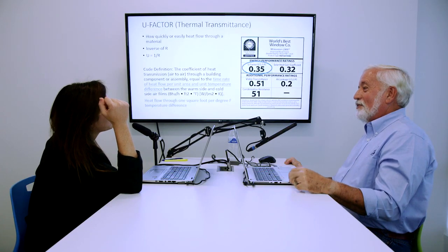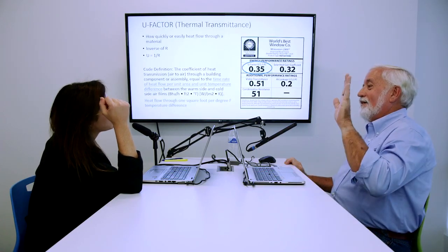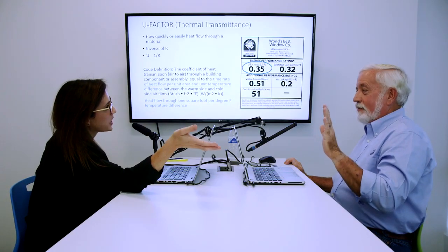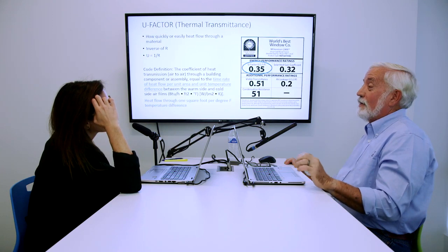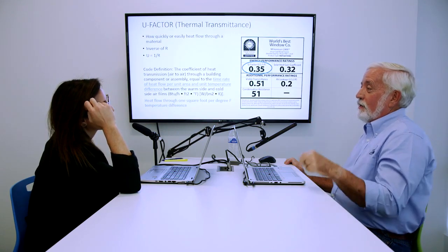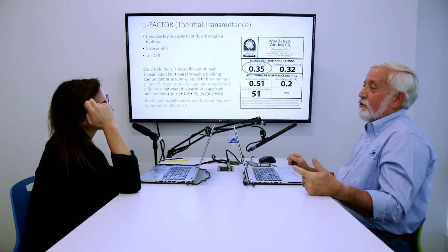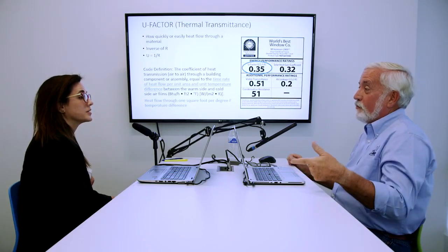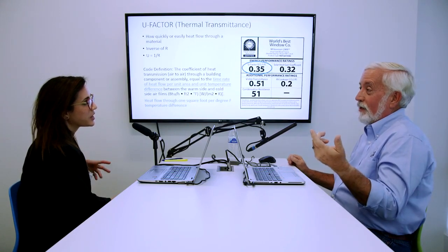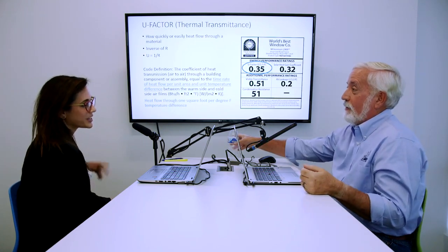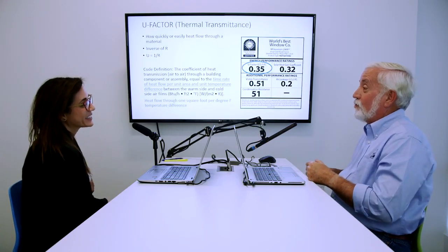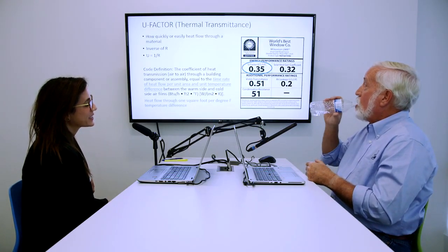So what does that tell us? That our windows are a weak component, and they'll always be one of the weakest parts of the house. In fact, a really good triple glazed window that has 3 panes of glass instead of 2 has a U factor around 0.2, which means 1 divided by 0.2 is 5. So a really expensive good window still is only an R5. And in price difference, is it even worth it at that point? No, they're not at this point. Maybe in the future they will be, but not at this point.